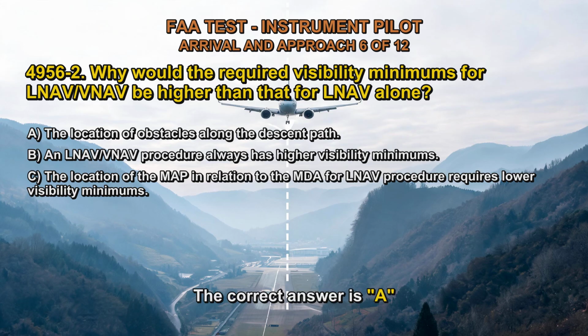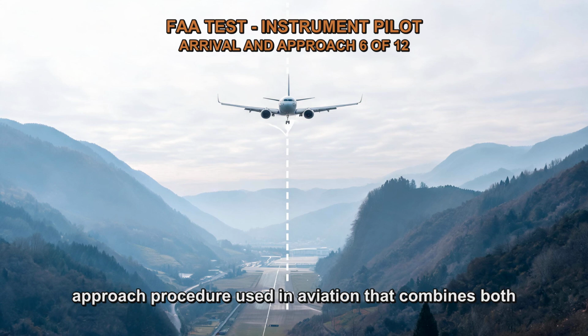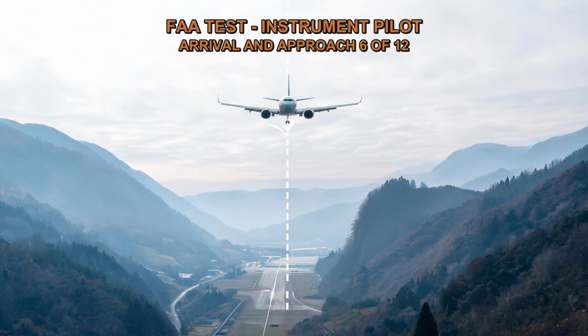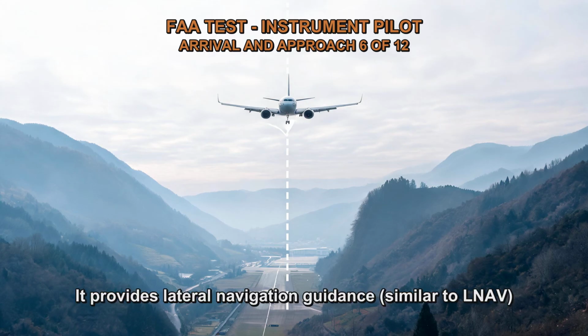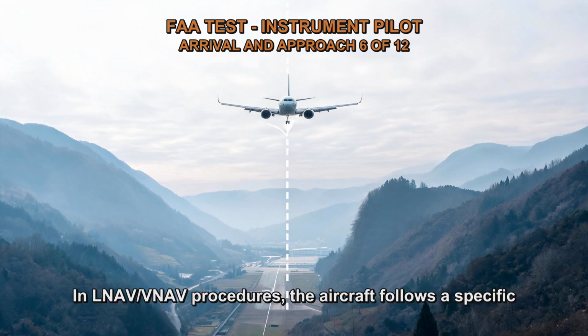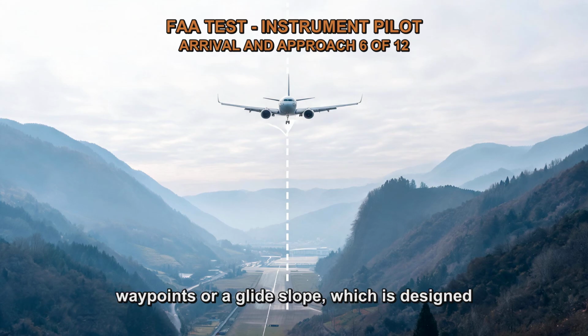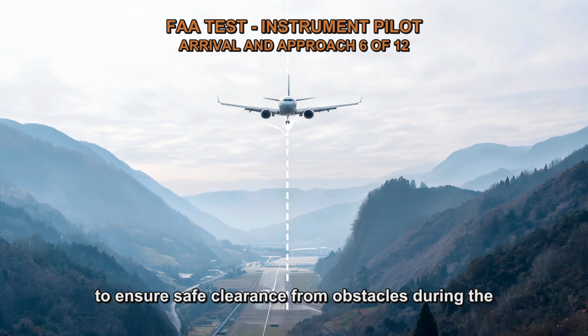The correct answer is A. LNAV/VNAV, lateral navigation/vertical navigation, is a type of approach procedure used in aviation that combines both lateral and vertical guidance. It provides lateral navigation guidance, similar to LNAV, as well as vertical guidance to assist with the descent path to the runway. In LNAV/VNAV procedures, the aircraft follows a specific descent path, often defined by a series of waypoints or a glide slope, which is designed to ensure safe clearance from obstacles during the approach.